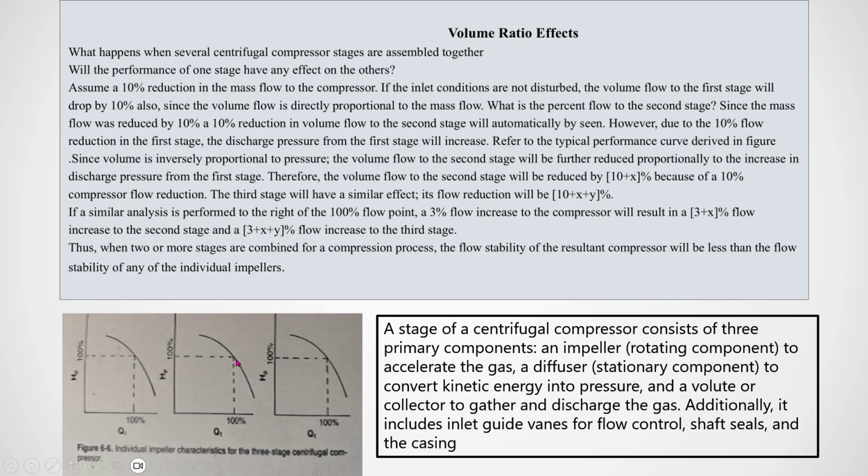When the inlet volume is reduced, the discharge pressure will certainly increase, and the volume will decrease proportionately. That decreased volume will go to the second stage inlet.